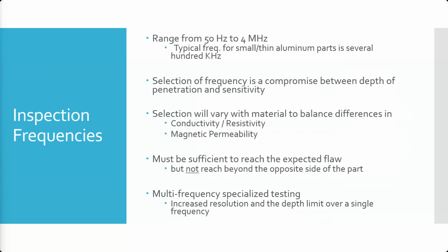Sometimes you use those higher frequencies for things like titanium or some of the other exotic materials, where you're trying to find very, very small flaws. When you're doing eddy current testing, you are looking for extremely small flaws. Because titanium, you're familiar with the titanium grain structure? Did they talk about that in materials? Why does titanium crack when you try to bend it? It has a crystalline structure that makes it particularly brittle. No? Okay. You know that titanium's brittle. It's strong, but it's brittle.